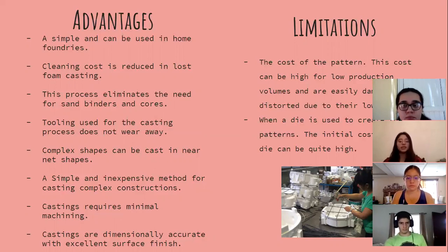On the downside, we can see that the cost of the pattern can be high for low production volumes, and it can be easily damaged or distorted due to the low strength. Also, when a die is used to create the patterns, the initial cost of the die can be quite high.